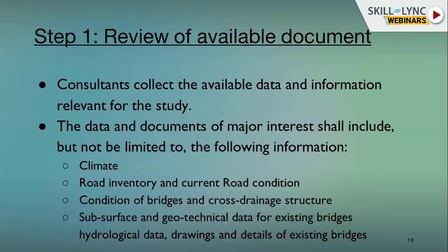Step 1 is review of available documents. Consultant collects available data information of the study. This includes actually existing road conditions mainly. What is the subsurface condition? What is the hydrology condition? If there is any existing bridge, what is that condition?